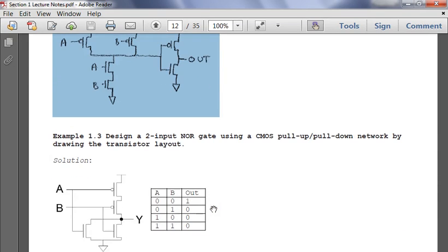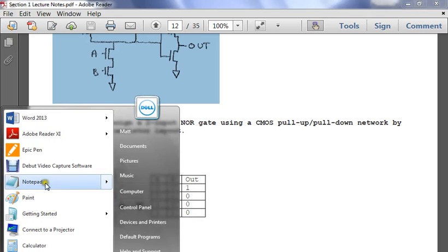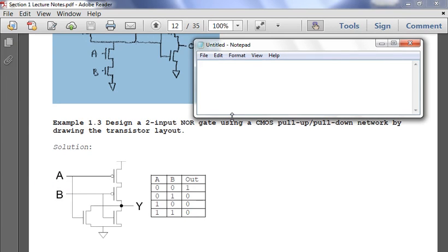And we will conclude the problems with designing a 2-input NOR gate. So here, kind of doing the same thing, we can do NOR A or B. So they started out their OR, so it's parallel, right? So the nMOSs are going to be in parallel, as we see here. They're in parallel.